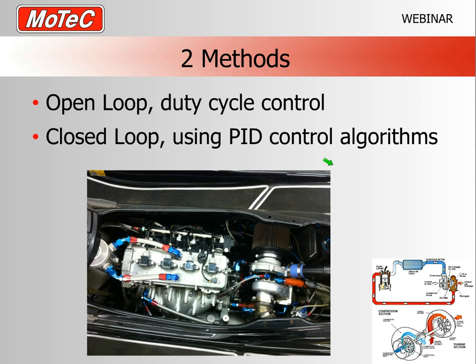But if the turbo gets a little bit tired, maybe you go change altitude, you're in South Africa, you go up and down there, that will change the amount of actual boost that the engine would have or make, depending on the altitude, depending on the turbocharger. So what that might mean is that 60% duty in one area might make 1 bar of boost, but you might travel down to sea level and it might make more boost. So it's a reasonable way of controlling your boost, but if you don't keep an eye on it, it might not necessarily give you exactly the same result every time.